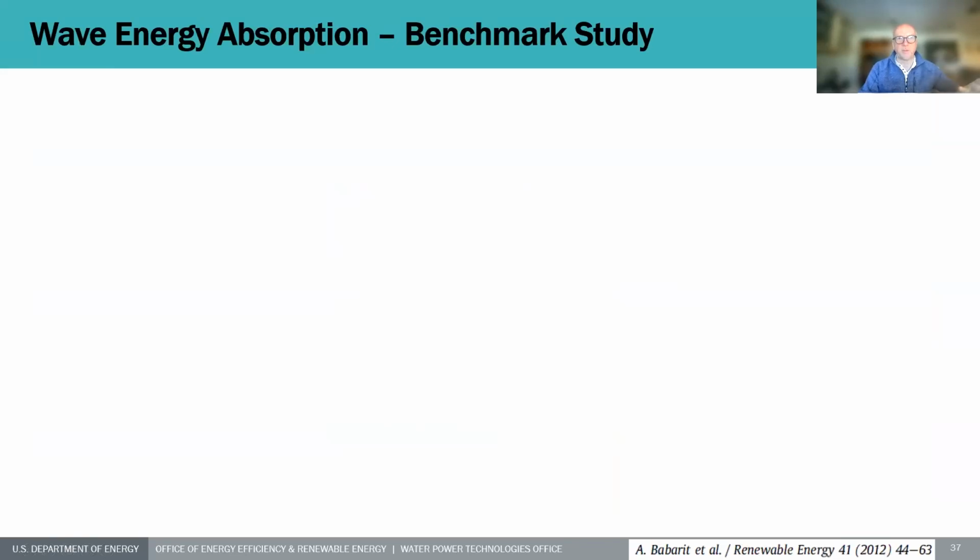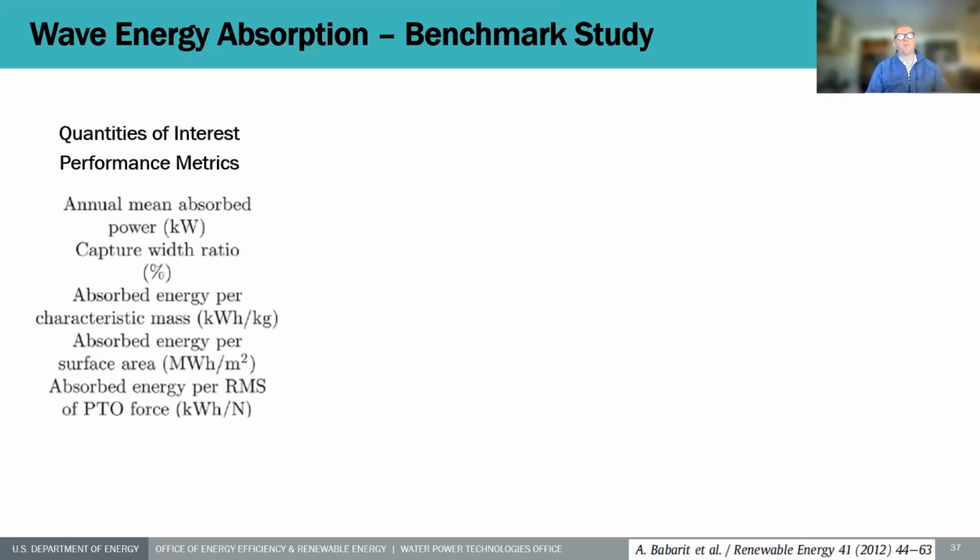Okay. Now, here's an important benchmark study. I want to point towards it. When we look at comparing technologies with their wave energy absorption capability, it's important to look at the annual average absorbed power. But this is not a relative quantity. It's an absolute quantity, which is, of course, a bigger device gets more out, I presume. But we want to have efficiency values. So we need to relate our benefit, the kilowatts, to some kind of a burden.